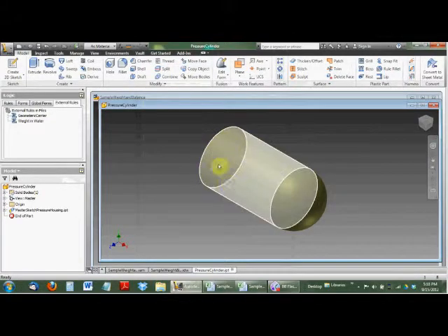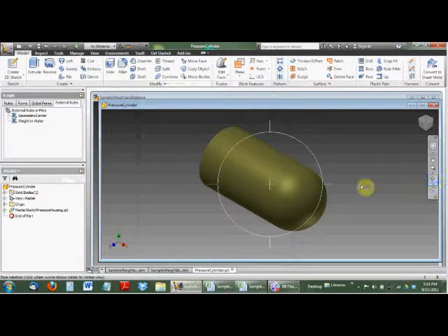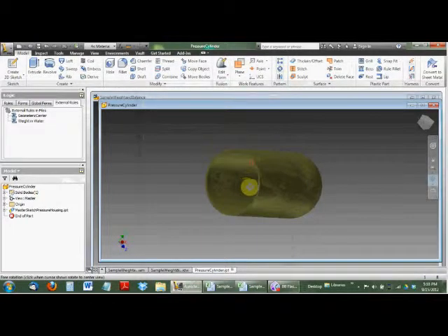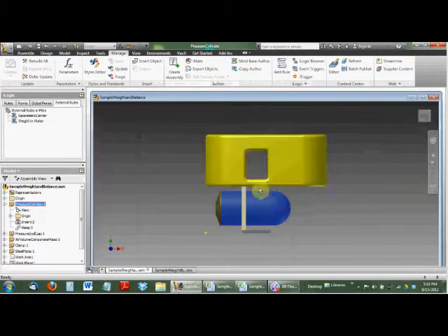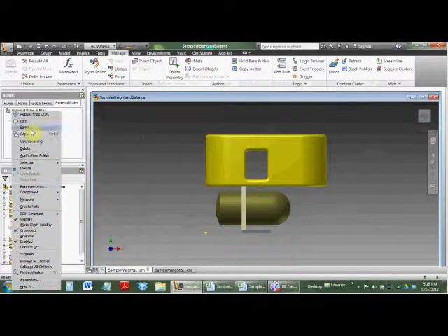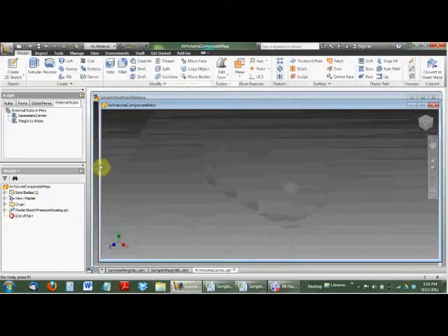So one of the tricks to making this work is, we have this cylinder here, and in our world this would be a supported void. In other words, the water external to the cylinder would not go inside, right? And we have in the assembly an end cap on this cylinder. We have the cylinder. So it's important to model the air inside that cylinder. So we're going to open up our little air model here. Okay, and this is what the air inside the cylinder looks like.